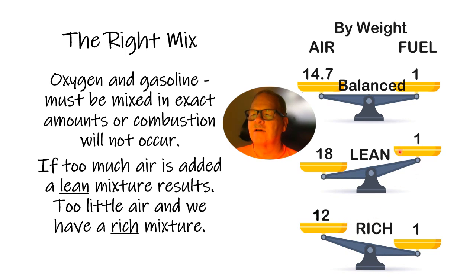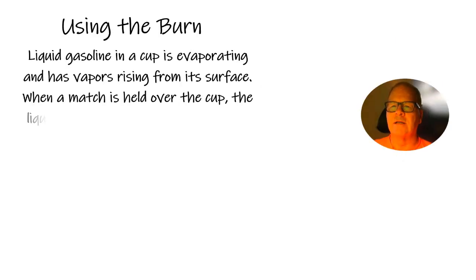And so you're basically going to have not enough fuel here in a really hot mix that's making oxides of nitrogen, because your combustion chamber goes above 2500 during the burn. And then rich is too black. I mean, it doesn't make black smoke unless you've got hydrocarbons coming out of there. You don't see the carbon monoxide, you don't smell it, but it's there because you don't have a good clean burn. Anyway, that's a little graphic I put together.